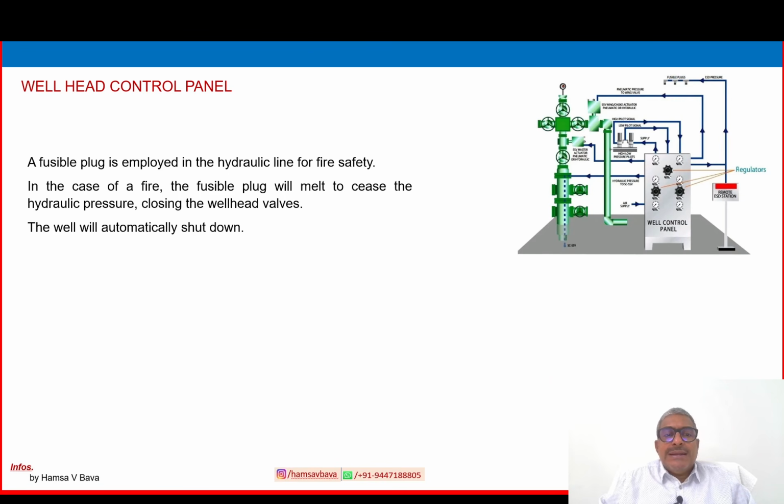The plug will melt when the surrounding temperature increases above a certain level. So it will automatically take action to close the corresponding connected valves immediately. Ultimately, the well also will shut down.